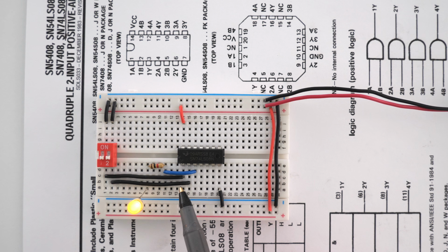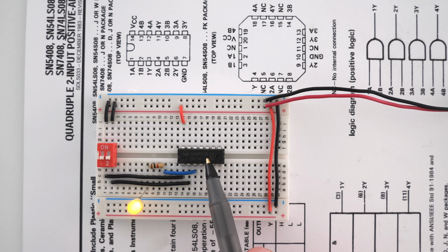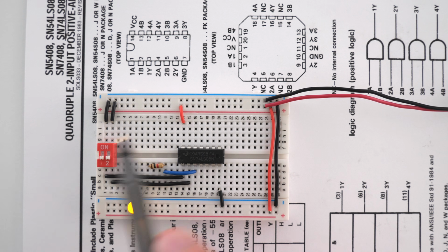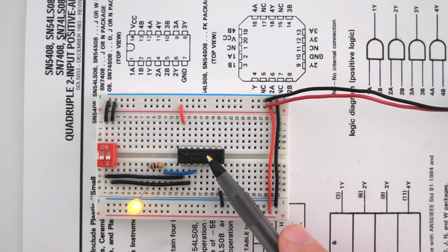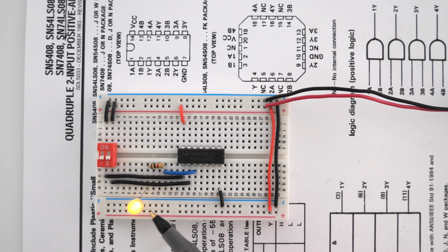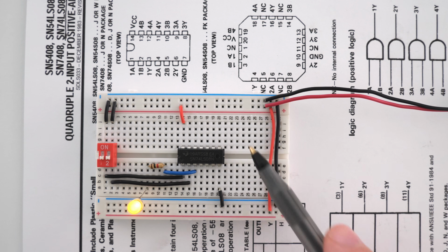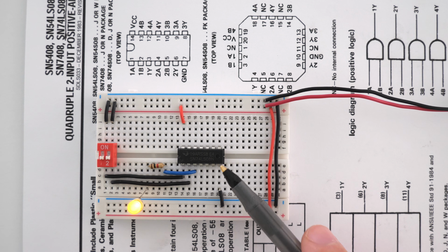The reason that these are on by default is there's a pull-up resistor within this integrated circuit that makes it so if you have no input into the input, it's actually on rather than off, which might seem a little strange, and you'll see a lot of people wire up their integrated circuits this way. I don't particularly like it because sometimes this TTL logic works and it's stable, and sometimes it does not. So you'll see this LED flickering a lot, so this is not how I recommend wiring up these integrated